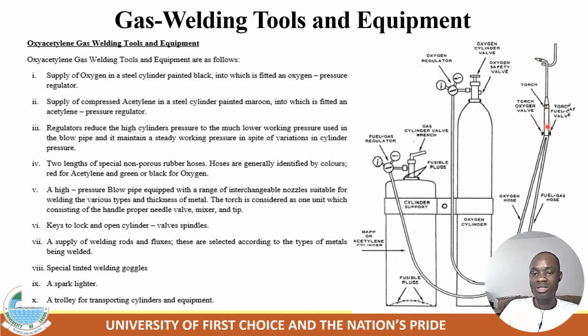This one is a welding torch. It has one orifice, and also it has 2 valves here that regulate acetylene and oxygen. So the valve that regulates the oxygen is coated black or blue in color, whereby this one is the acetylene cylinder that contains acetylene gas. So it also has a regulator here, fitted with 2 reading meters.